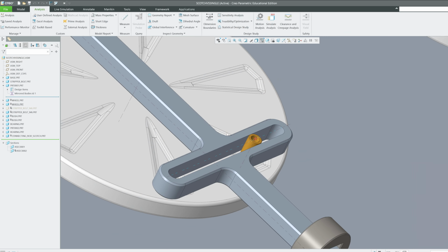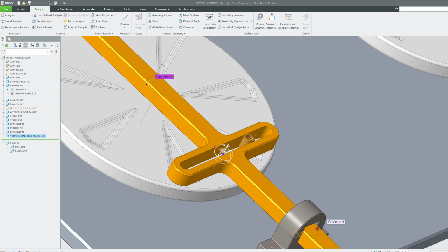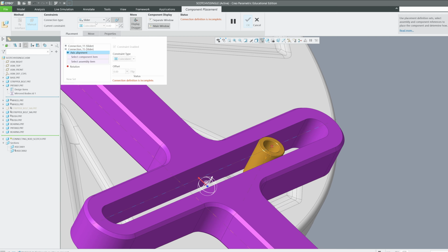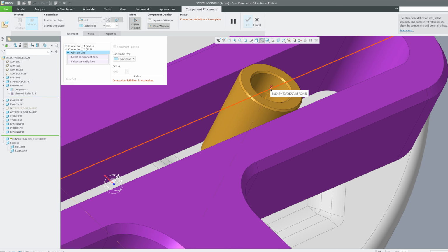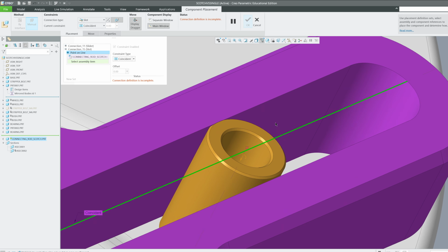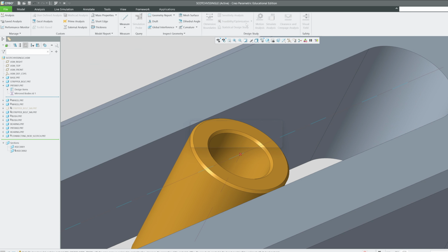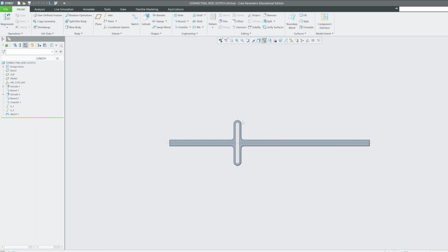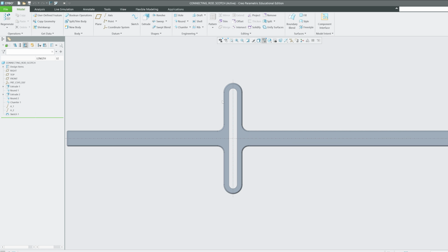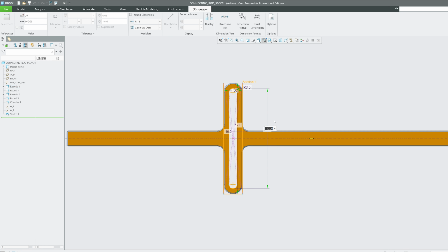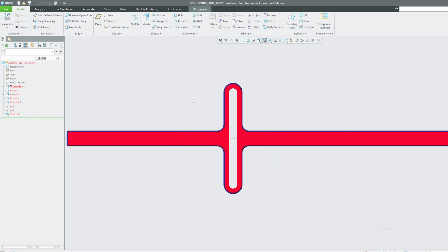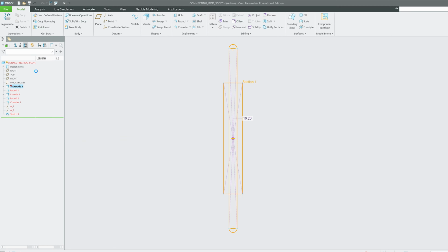Now go back again. The connecting rod does not yet have complete degrees of freedom constrained. Let's go New Set and let's go Slot. Now I'm going to choose the connecting rod and the point, and now it is properly constrained. Now if I rotate this, it will behave like this, but the slot width is not enough. So let me increase the slot width here. Let's make it this much. I don't know why it is failing. It shouldn't fail actually.